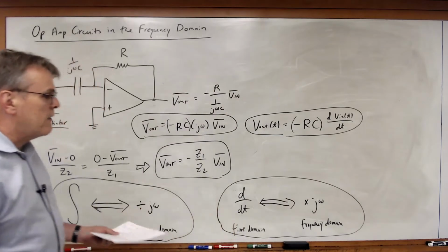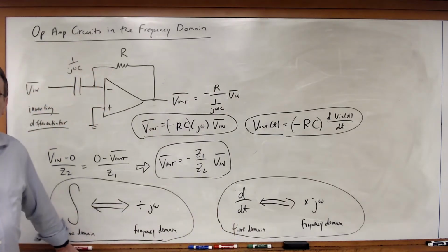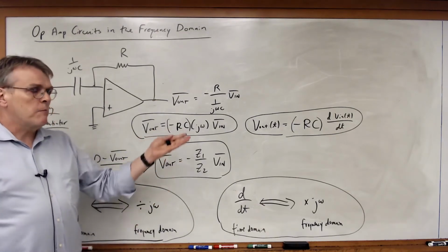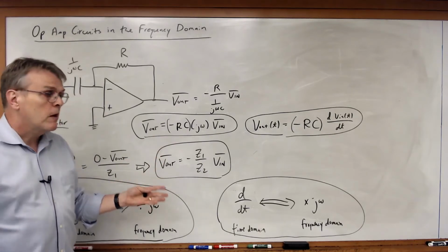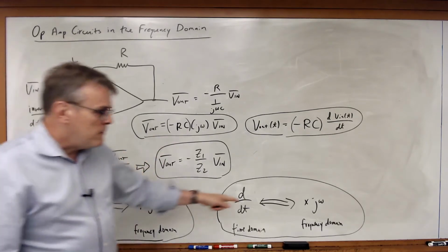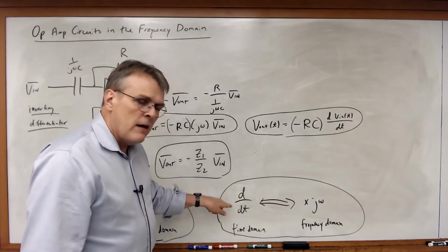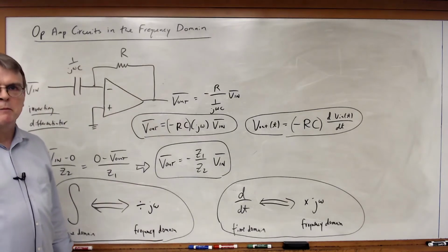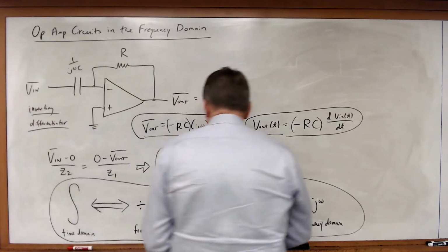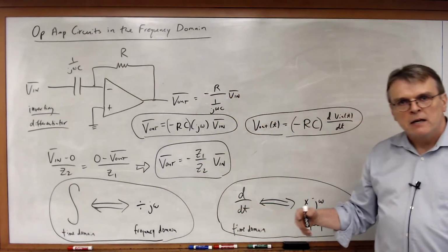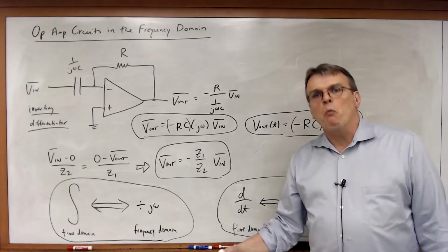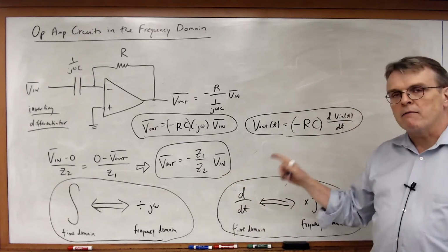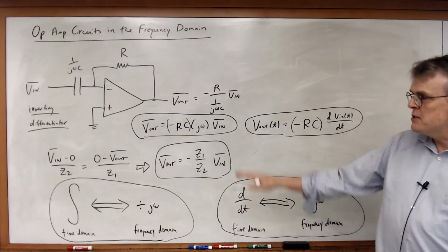So here we really understand why the frequency domain is so important, why we study this, and why if you take more advanced courses in signal processing, you'll learn about Laplace transforms and Fourier transforms, which operate along the same idea. You move into the frequency domain, and calculus turns into algebra. Complex algebra, but much, much simpler to manipulate. And this is why these techniques of phasor analysis, of Laplace and Fourier analysis, we use them so much and why they're so powerful as tools, because they make a lot of very difficult math much, much easier. And this is just a perfect way of illustrating that.